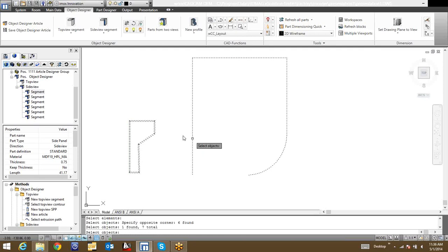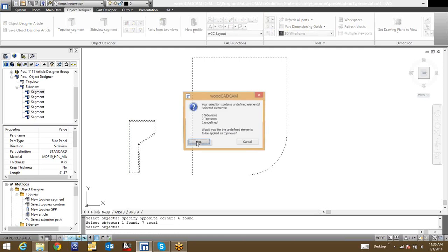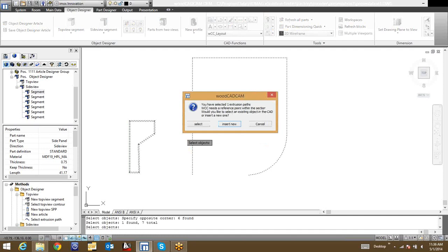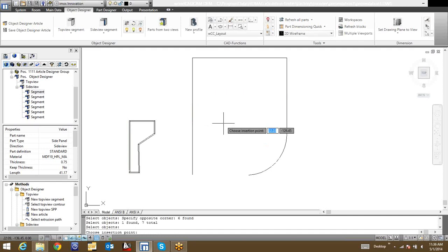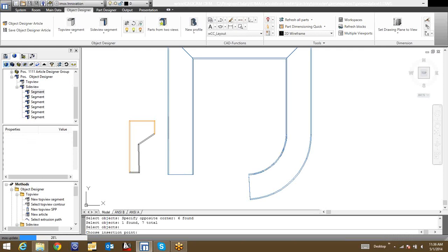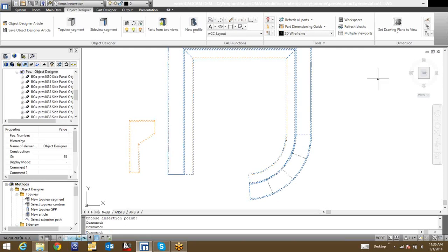It seems like it's just extruding that sectional view, which is good, along the polyline. So on the left you've got the section, and on the right you've got the polyline. So he goes ahead and chooses the insertion point of where the section view is going to run, back bottom left, and then he chooses the polyline, and there it is, done.